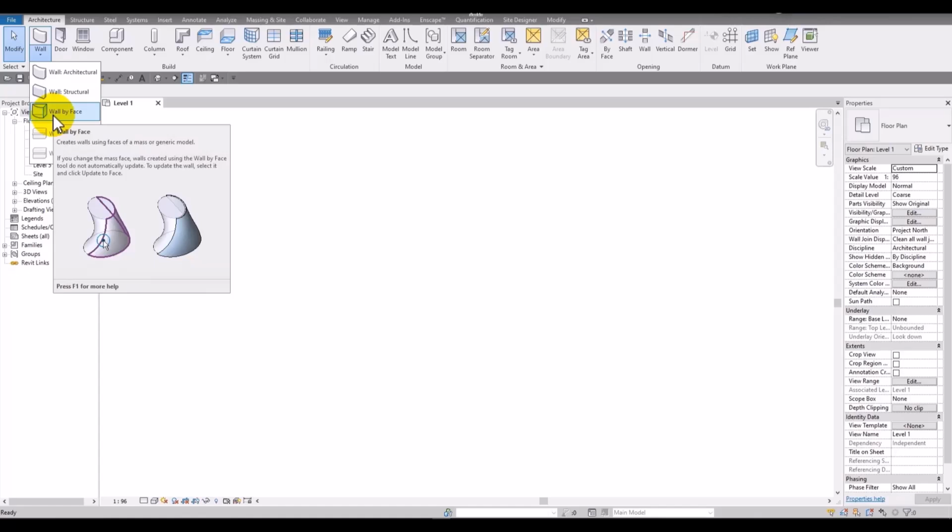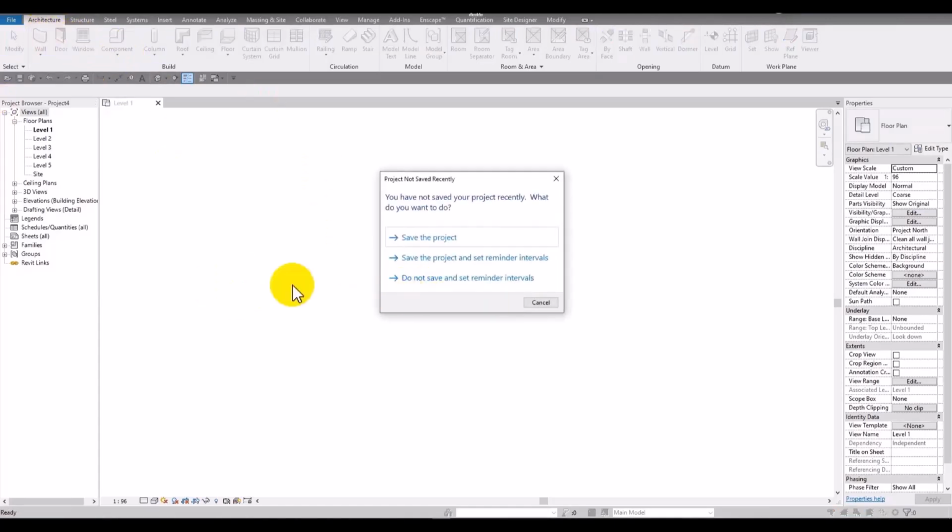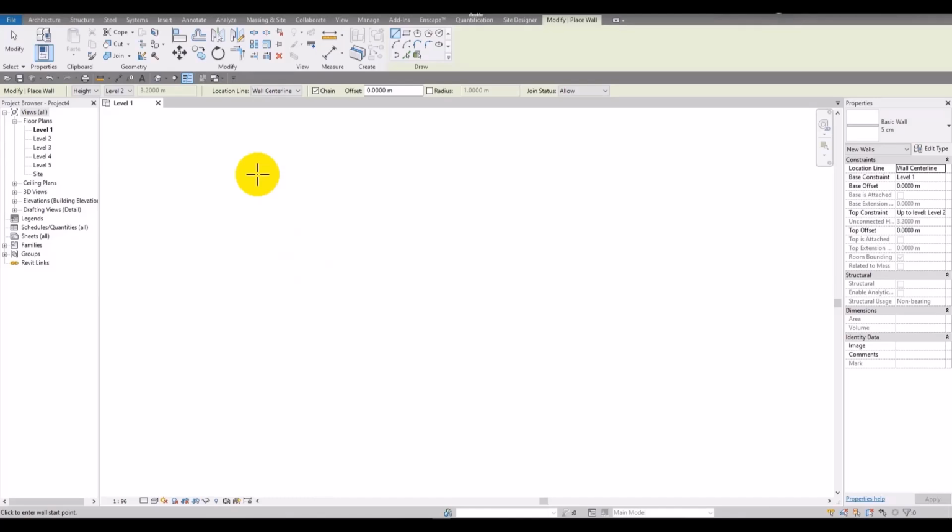Right now, in the normal situation, when we click on the wall or use its shortcut W and A, both of them are the same. When this section, Place Wall, is active, here in the Draw window, as you can see, all the modes which are possible for drawing a wall will be there, and some more items which you can see in the option bar. They are here temporarily. The default mode is line.